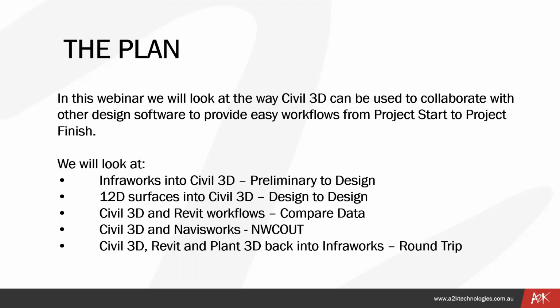Then we'll be looking at working between Civil 3D and Revit and getting those two coordinated, working together, seeing Civil 3D in Revit, and Revit in Civil 3D. Then taking all of that through to Navisworks, so we can see everything compared together in Navisworks as well, where you do your clash detections and things. And then round trip everything back into Infraworks at the end for things like public consultation of your proposed projects, etc. So it doesn't look like much on paper, but it's going to take a little while to get through, so better make an immediate start and get into the demonstration.